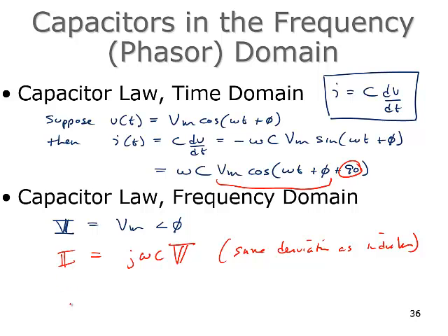But since we normally express these as V equals something times I, then we can derive our essentially Ohm's law for the capacitor: V equals I over j omega C. Or if you don't like a j in the denominator, you can multiply top and bottom by j, which gives you a minus 1 in the denominator, or V equals minus j over omega C times I. And now this is across a capacitor, right? And what this means is the voltage is going to actually be 90 degrees behind the current, because the current here is what's advanced, right?